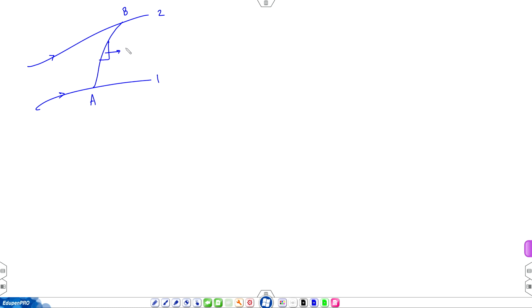This is the u component of velocity, and this is the v component. u is the x component of velocity, v is the y component of velocity. So, those elemental lengths, u dy. We are doing a 2D calculation, so it is unit dimension normal to the plane of the blackboard. So, u dy is the little flow crossing a small element ds of AB in the x direction, and v dx.